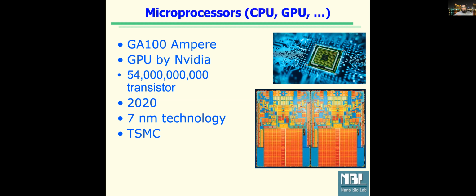All the steps involved are what you have in Soft Chalk, some derivative of those processes. Soft Chalk, the lesson on silicon fabrication, talks about basic processes. But when you go to such a small size, we have to make many modifications to that process. For example, they don't use optical lithography because light cannot cut to that small resolution.